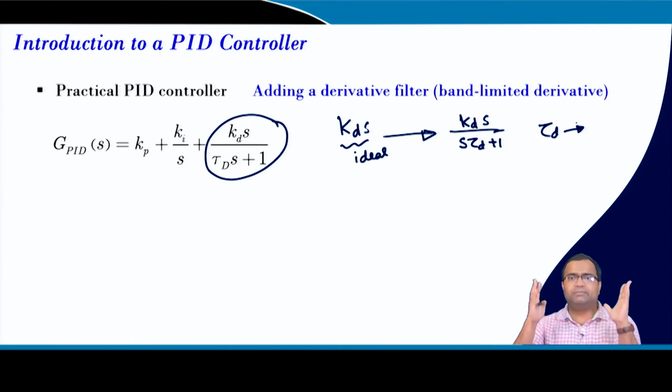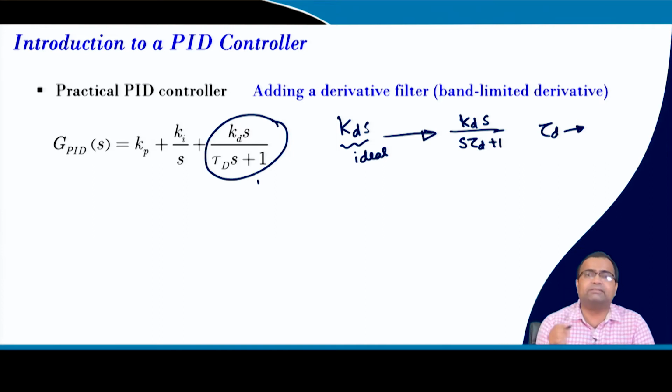Of course, it will put a limit on the bandwidth, because generally this comes from the op-amp bandwidth. Whenever you are talking about, let us say, a 1 megahertz converter, we take some hundreds of megahertz op-amp as an error amplifier. As a result, the op-amp bandwidth is pretty large, but sometimes we may not even want such a high bandwidth for the derivative filter, because we need to attenuate certain switching noise. In that case, we may want to increase tau d slightly.